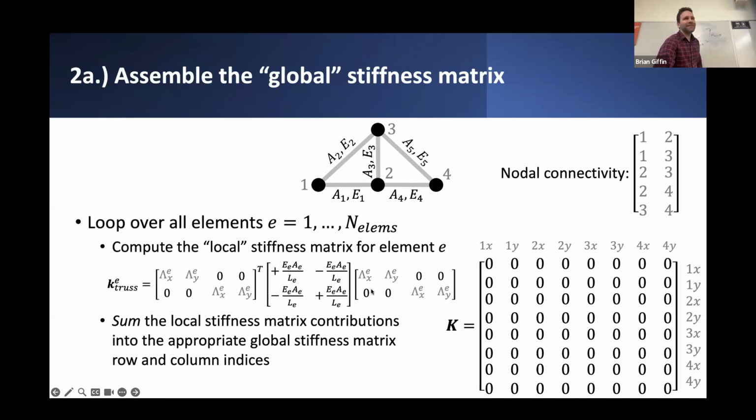But we have to left and right multiply this by these transformation matrices. Essentially, these matrices are like a coordinate transformation that takes our one-dimensional element, which is nominally aligned with some local element coordinate axis, and these transformation matrices rotate that element effectively into the global coordinate system. That's one way that you can interpret this operation.